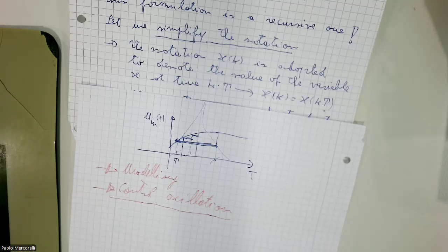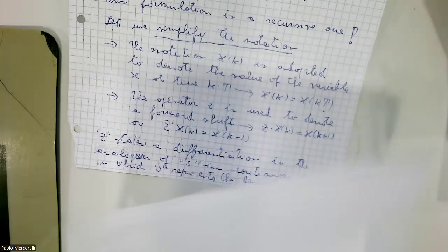If you want to get information from a very fast signal, you need to sample very fast, much faster than the phenomenon. In photography, I don't know if you know a little bit the photography technique, if you want to shoot a car that is running really fast, you have to program the opening time, which is our sample time, very short. Otherwise, you don't see the phenomenon.